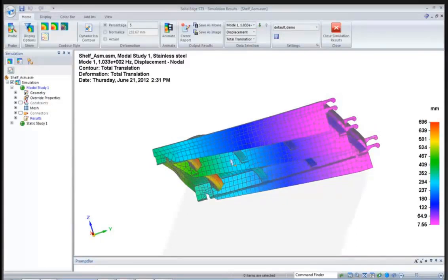So what I did is I added another bracket there, because now it's constrained. So now it's stiffer here because it's constrained here in the middle. And I didn't increase the mass too much, and I actually went to a 20 gauge sheet metal, which means my part is now considerably thinner. My parts are now considerably thinner than they were, so I'm saving in material costs.